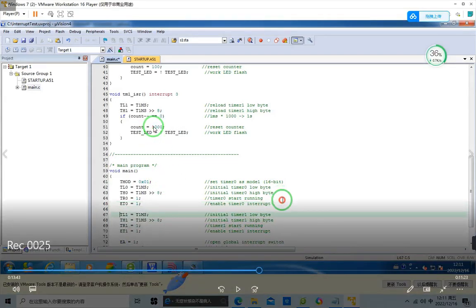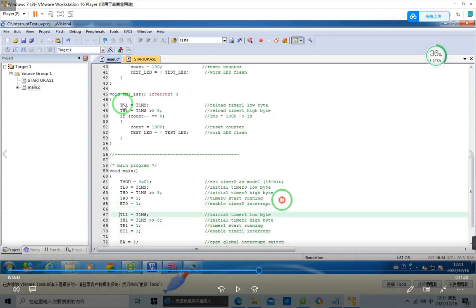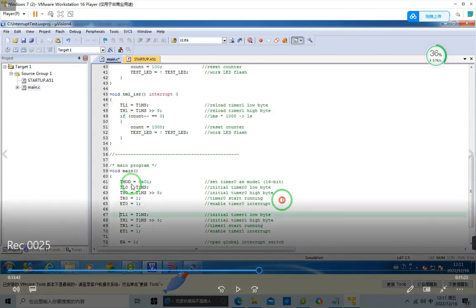One thing I want to mention here is the interrupt routine. Here is your main routine. The interrupt routine is separate code. You see it right here. It's separate code, only triggered by the interrupt itself. It's not arranged by our main logic. It's outside the main function, and it's not called by any code in the main function.